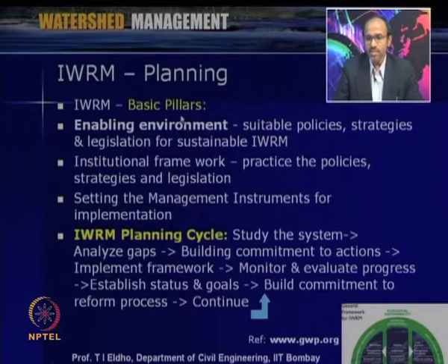So if you consider the various aspects of integrated water resource management, as far as IWRM planning is concerned, we can put it in a cycle. We have to consider the particular system, whether it is a watershed system or river basin system. Then we have to see what the issues are as far as the system is concerned. Then we have to analyze the gaps in resource management, and build commitments to action so that we can remove these gaps and make better management plans.